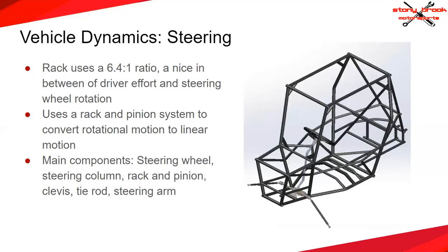The rack and pinion is fundamental in transforming rotational motion to linear motion. Once the rack moves either right or left, that has an impact on the tires because you have tie rods that connect to the rack and also to the tires. So once you rotate, that's the path that everything goes in. In this system, we make most of the components.